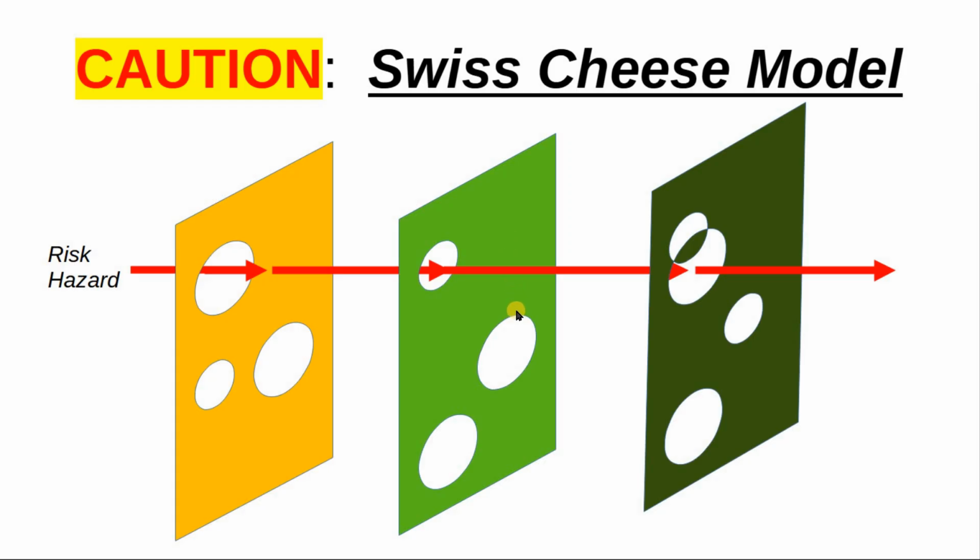He may touch the pipe and the pipe is very hot, they can have an accident there. So to avoid this, they said as a blanket statement, anything more than 60 degrees C within 2 meters from the ground, insulated, regardless of the application. Now, if you find this somewhere, that's fine, but this will not be in the vendor's installation drawing. Typically, it's not in the code. So something like that will not be addressed unless someone in the company went through it and then advised us to do it.